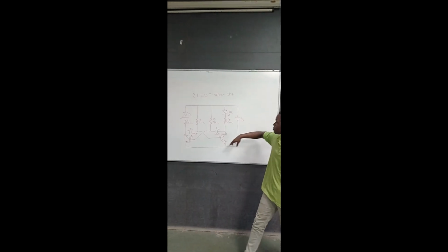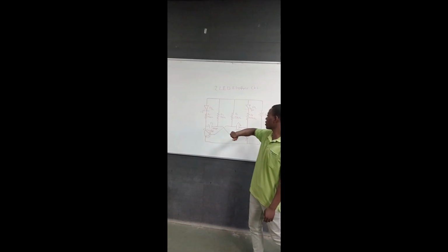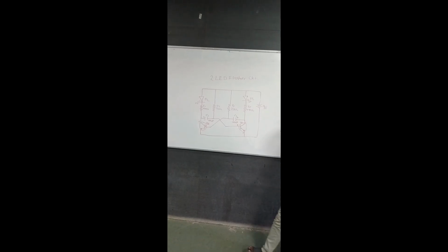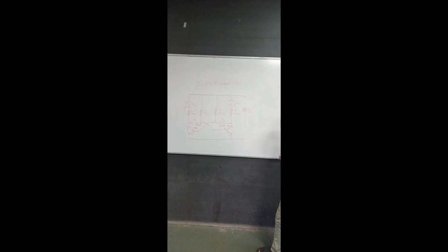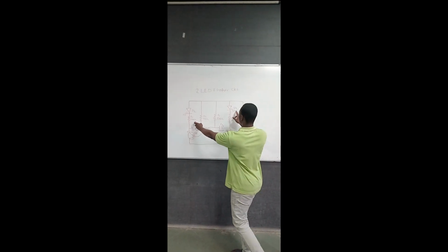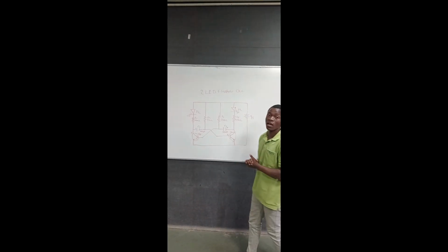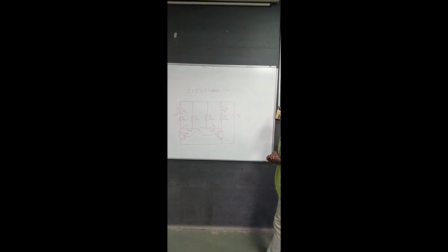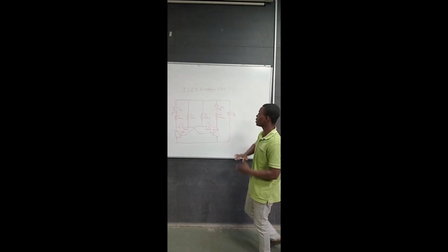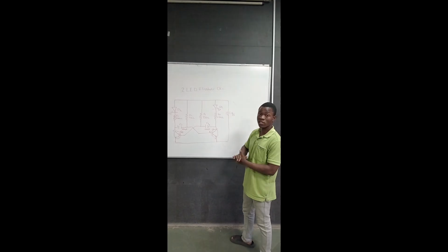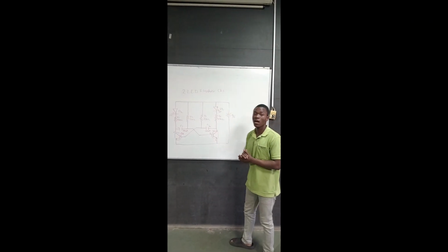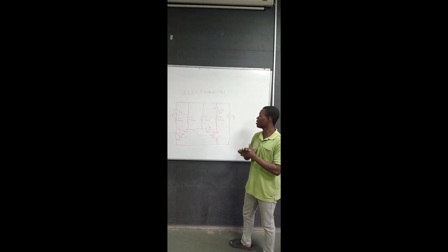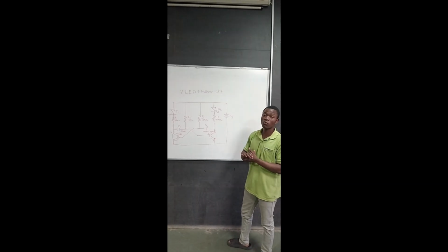Then let me go to these resistors, R1 and R4. Both of them are 470 ohm resistors. These resistors, as you see, are connected in series with the light emitting diodes. So these resistors ensure that the light emitting diodes receive a safe amount of current.